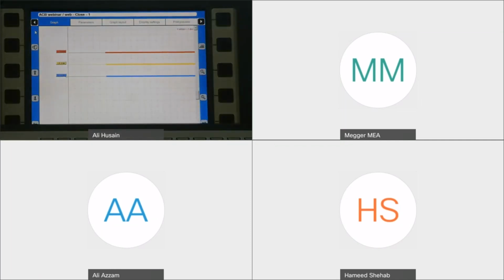Now, this operation of the breaker is done for this kind of breaker only for close and open operation. But for any breakers in the medium and high voltage, you will also require to do, I would say, the other sequences like open, close, close, open, and open, close, open. Due to the short time that we have, we will not be doing these, but they will be showing a similar way of operation where you will connect, you will measure, and the control will automatically generate the pulses required for this kind of operations.